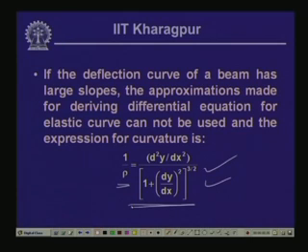Hence, the expressions which we have derived here are suitable for small deformation only, and for large deformation this is not applicable. We will have to use the curvature in terms of these expressions. We are not going into the detailed derivation of this, but for your information, for a large deformation of the beam, the curvature term is to be used with this particular expression.